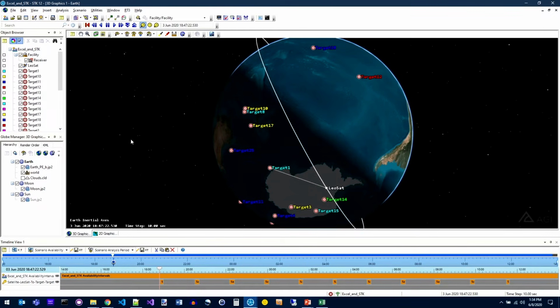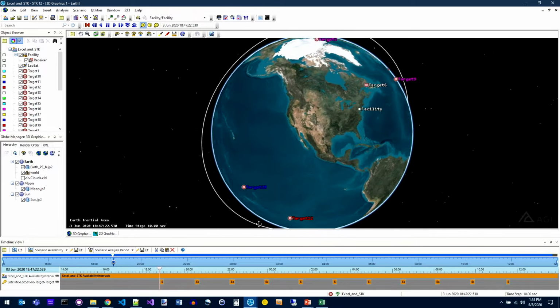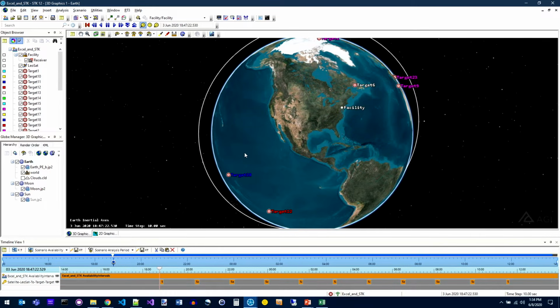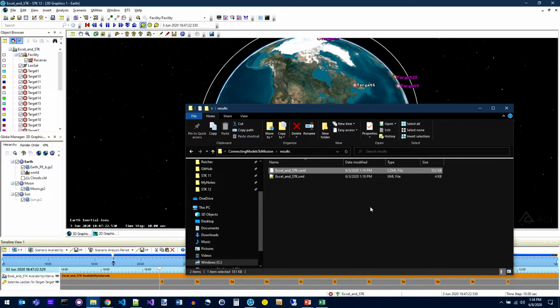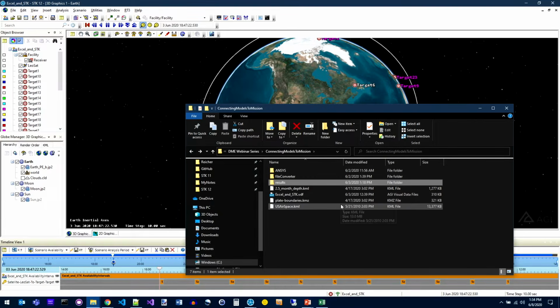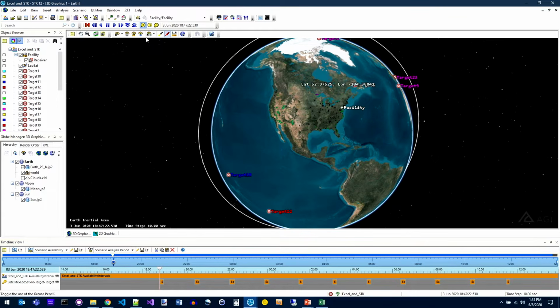Now when it comes to the other types of objects in this scenario, or the other types of GIS information, it's not just the terrain data, but also things like shapefiles to define where specific types of objects are in the scenario. One of the things that I'll pull in here to my scenario is, instead of the shapefile, a little bit more common file format that you see being created out there, and that's the KML standard. So I'm going to take this US airspaces KML, just drag and drop that into the STK window, and you'll see that the visualization here is already available.